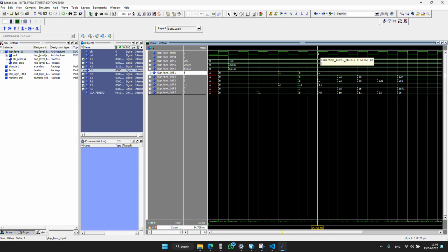That means we should always look at the maximum number of clock cycles it takes. If you remember Newton Raphson, it took us 12 clock cycles because there were 12 stages. Now here it takes us a maximum of 8.5 clock cycles, which means this is faster. So if your program is faster, this is the one that you should use. If your professor asks which one is faster, non-restoring. But as you know, it outputs in this way and not exactly in the square root form that we are used to. So this is currently working as in the long division method.